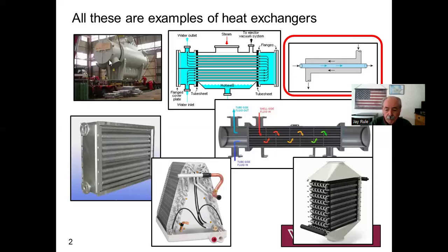Okay, back to the power plant condenser, actual picture. One of the substances is steam coming out of a steam turbine at a very low pressure, and we're trying to condense that steam. And the other substance would be something like river water or lake water, some type of cooling fluid that's absorbing energy from the steam in order to be able to condense the steam.